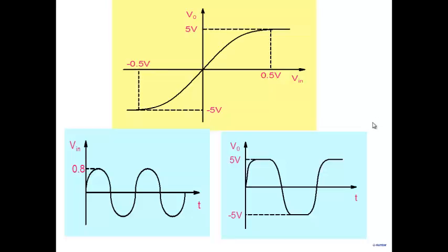So what is really happening, what we are saying in another way, is if you drive your amplifier starting from lower voltage, the amplifier is increasingly getting nonlinear. Harmonic distortion is increasing. But at a certain stage, you reach this limit, and that's the absolute limit, maximum voltage swing. At that point, you get severe distortion in the output. You start getting clipping, and your harmonic distortion would increase drastically at this particular point.